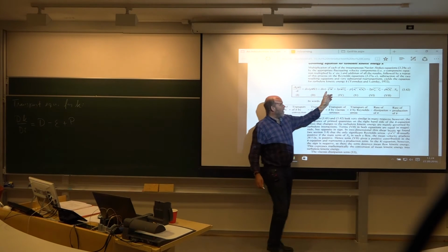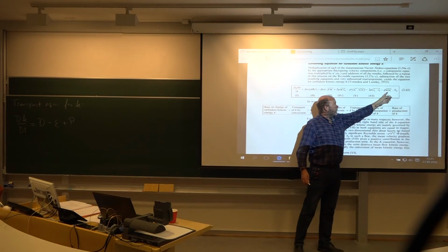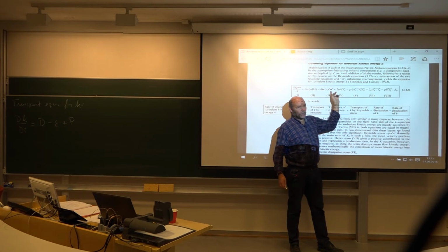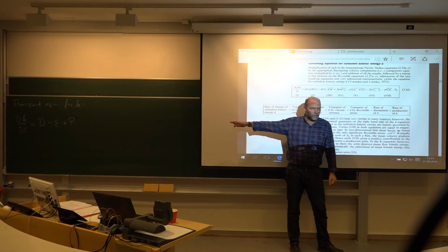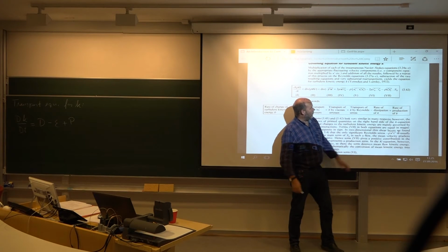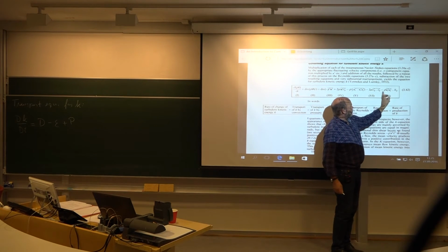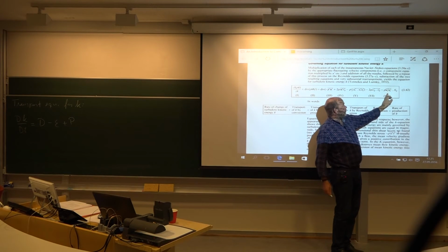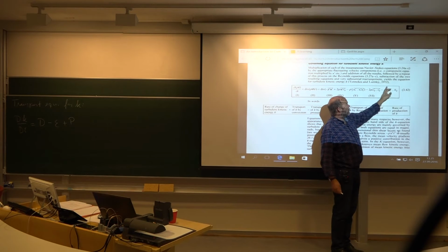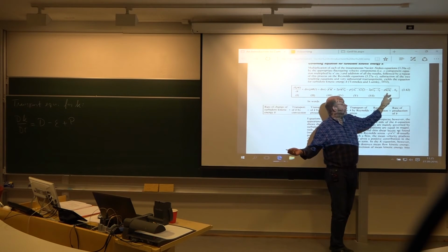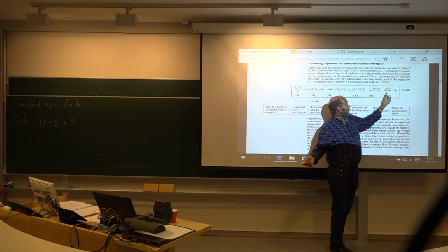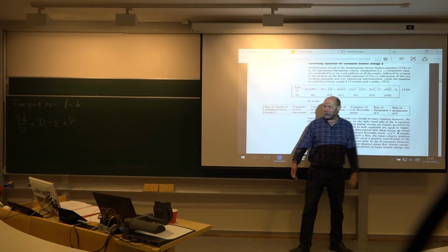Because this, we have no way to calculate these terms correctly. Just forget it. We could just as well have started with this equation, except the last term, this one we can play around with. This one we can get an exact expression for. Here you have the Reynolds stresses. So there you could use the eddy viscosity hypothesis to substitute here, using the eddy viscosity and so on.